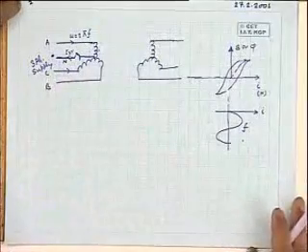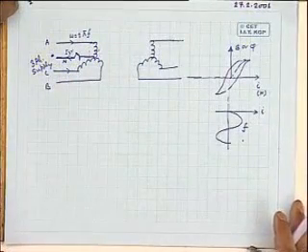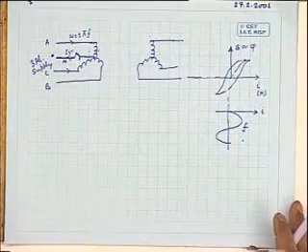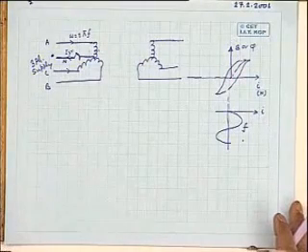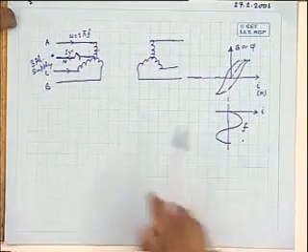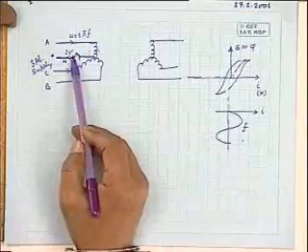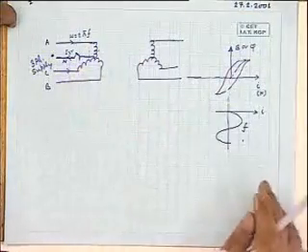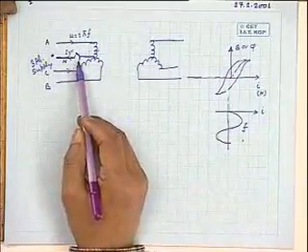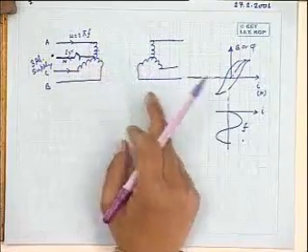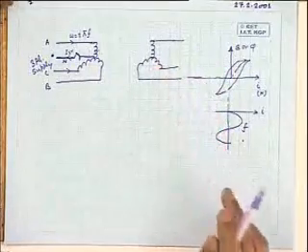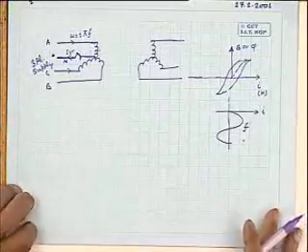And this may interfere with your communication wires, which may run side by side with your power lines, is it not? Along the transmission lines, the communication lines, telephone lines, are also laid. Therefore, this 150 Hertz component of current may interfere with your communication network. Therefore, this is not commonly used to make flux sinusoidal in the core in order to get sinusoidal induced voltage between the lines or across the winding. Another way of doing it is in this fashion.